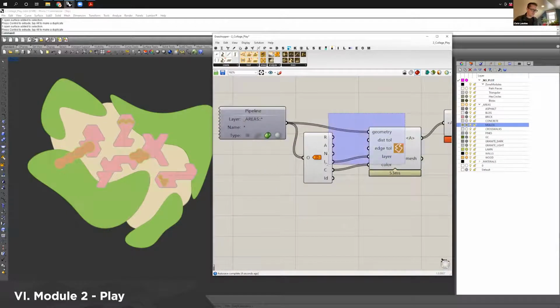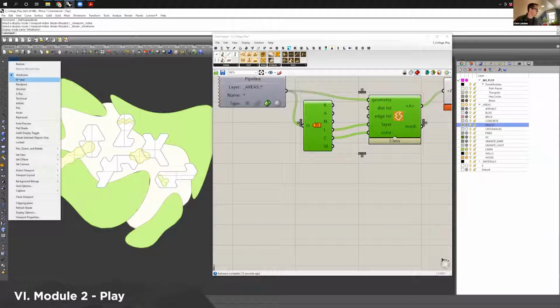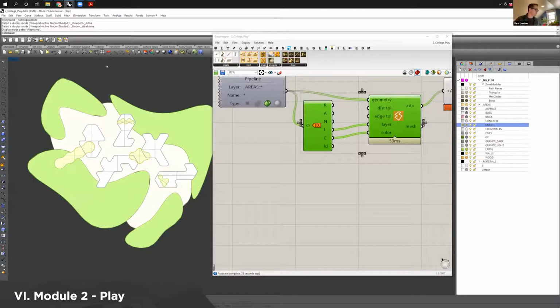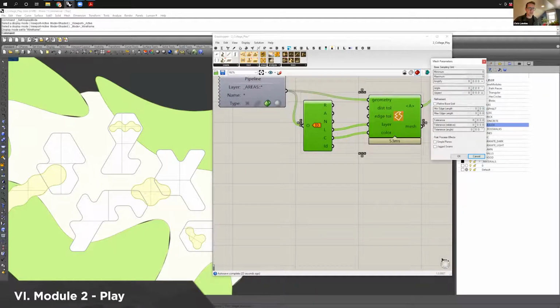And if I just hide this geometry, Control Q, and I do a wireframe view, you can also do wireframe up here. And I'm also seeing some weird edges, and that's partly to do with the detail settings in Grasshopper. So if I go in here, I actually like to just make all of this 0, 0, 0, and then I change the tolerance.